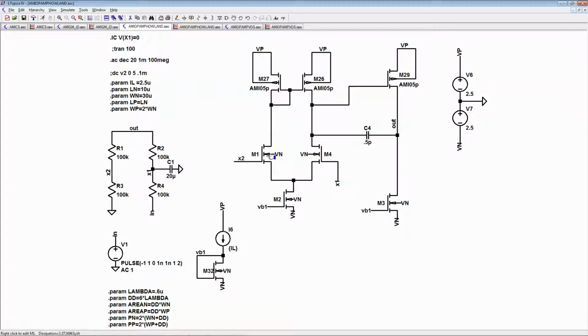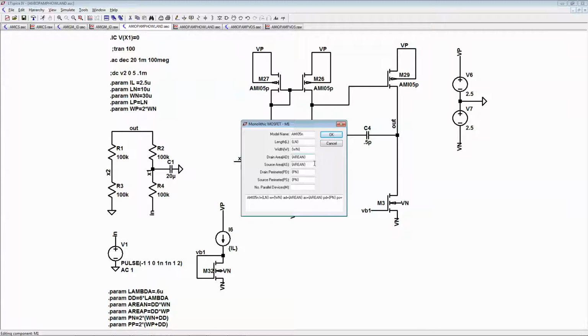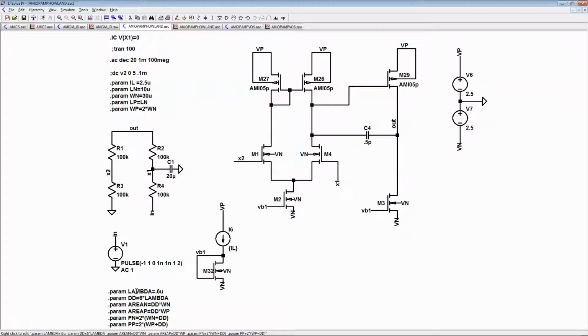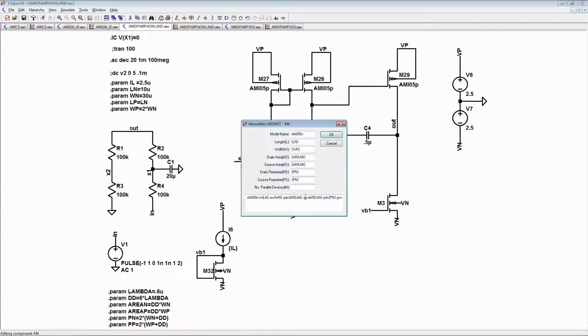something that I added to this simulation is that there's the area of the NMOS drain and sources, and the perimeter of the drains and sources, and essentially when we get into layout you'll see what these things are, but you have to calculate them, right? Now the thing is that assumes these fixed LNs and WNs, but if I want to study the mismatch, right, rather than try to adjust WN and LN, I can just make this 1.1 times bigger,